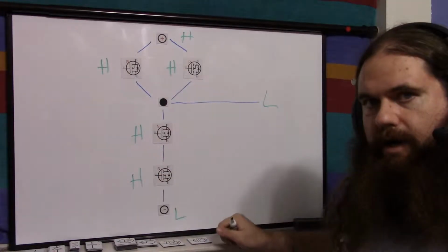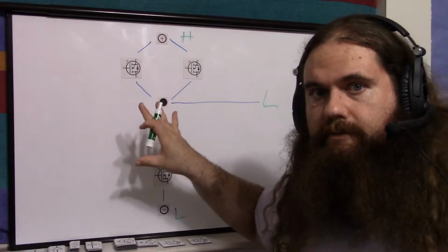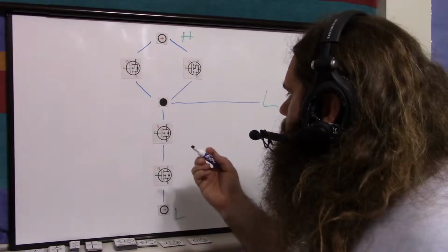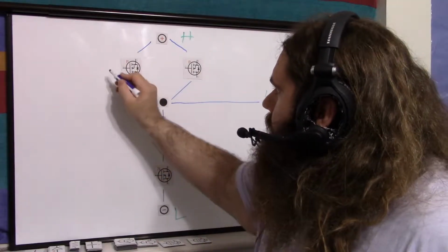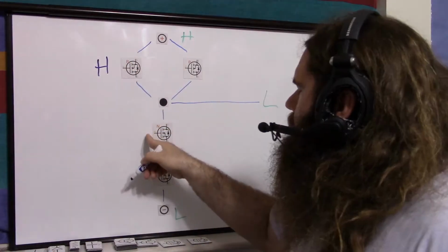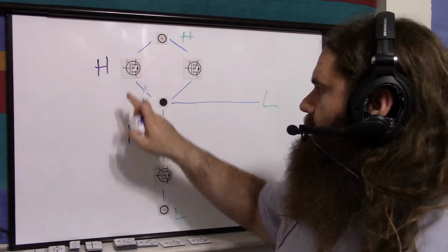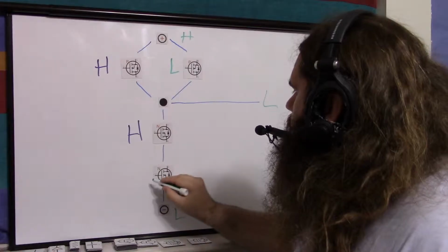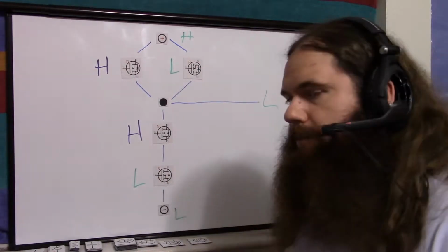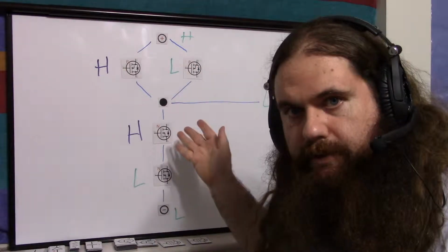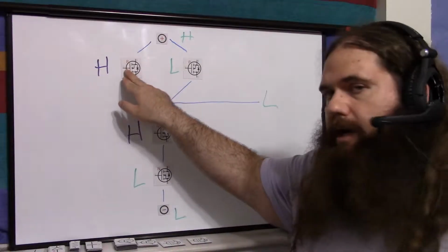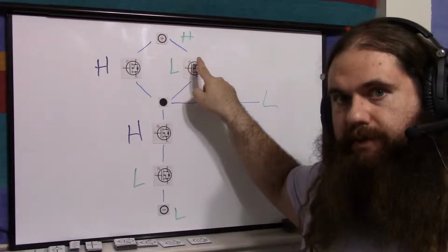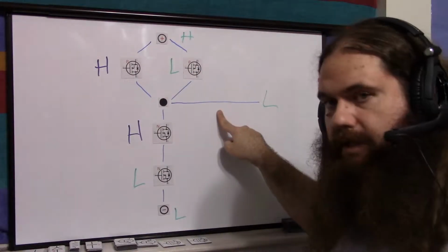Now, if we change either of these to low, now recall, this is 2 input. I'll do this in 2 different colors, if you can see them, to help. So on the left here, I'm going to say high, and on the top is high. So left P, top N is input 1. Right P, bottom N will be low. That'll be input 2. So what happens now? This is high, P-type high is still closed, but this P is getting a low, so it's open. So the positive is connected through to the output.